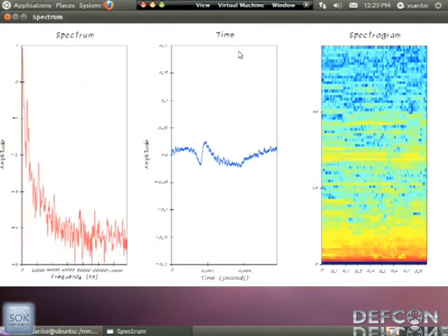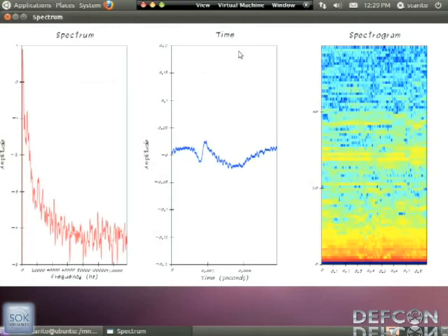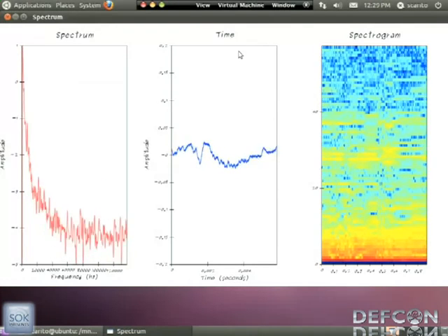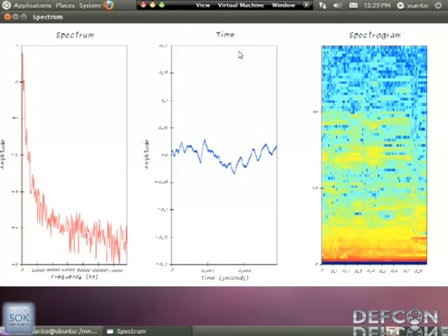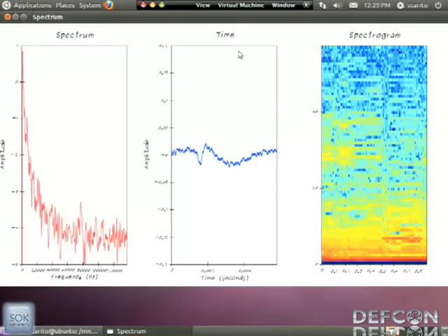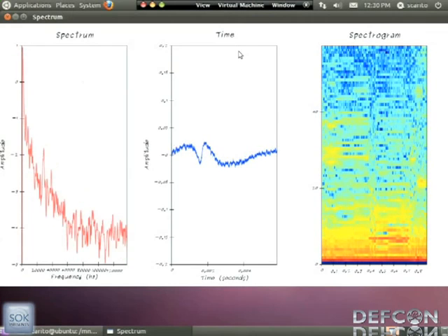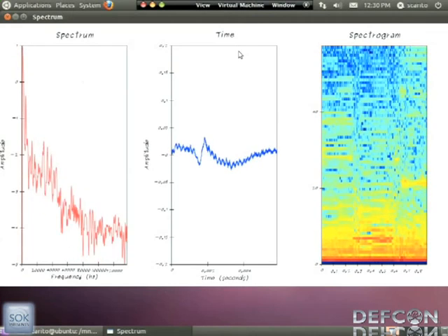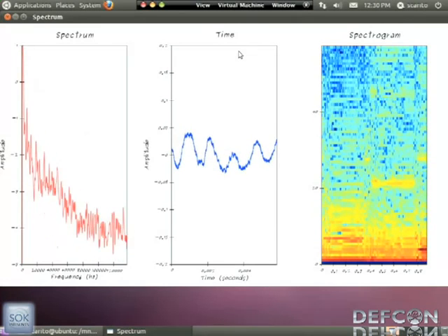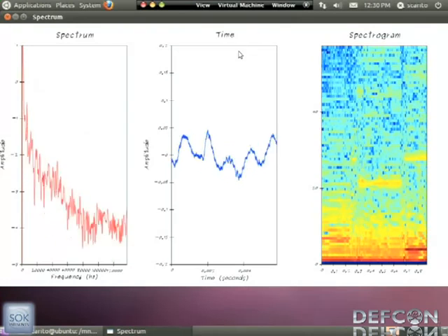So what I can do is if I point it at the wall, I'm pretty sure that strong response at about 30 meters is probably about the distance of that, which sounds about right. If I point it up at the ceiling, it's going to drop down, and we see a very strong red line at about 8. It's about the correct distance, and we can just scan it around. We get something at about 4, which is about right.